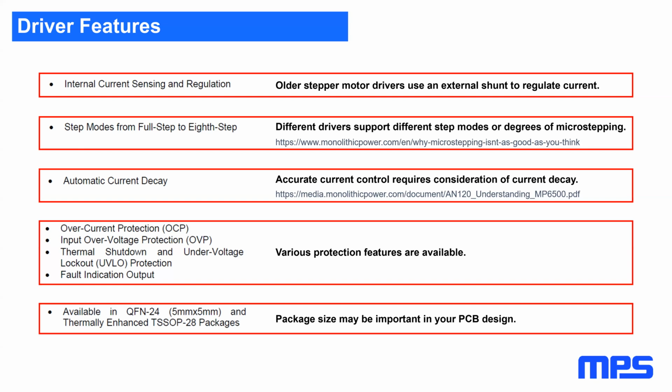The supported step modes vary significantly between drivers, anywhere from just doing full step up to 1/1024 step microstepping. To a point, finer step modes result in smoother and quieter operation, but often mechanical considerations limit the usefulness of very fine microstepping. For more information about that topic, read the article, Why Microstepping Isn't as Good as You Think, at monolithicpower.com.